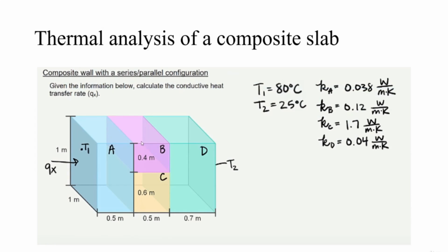In this particular problem, we are going to perform thermal analysis on a composite slab. Here there is a composite slab with 4 different materials, and here we are going to give the temperature, and here also we are going to give the temperature, and then we are going to give the thermal conductivities of these 4 materials. Then we try to find out the temperature distribution inside this composite slab, and also the heat flux that is generated at this particular surface of the composite slab using Ansys Workbench.